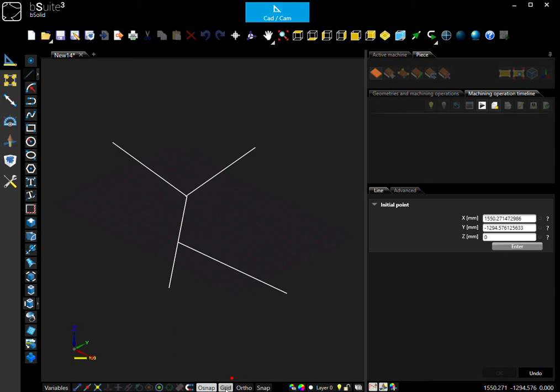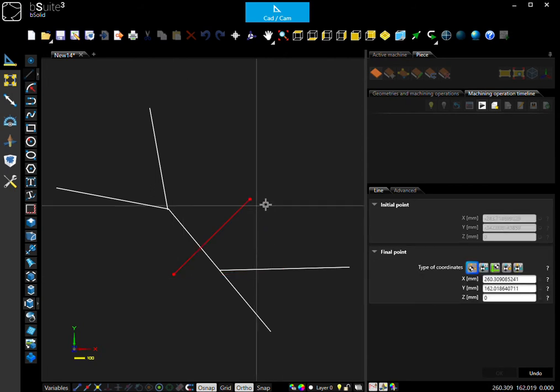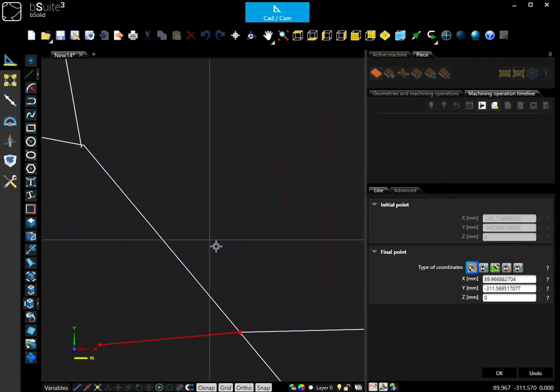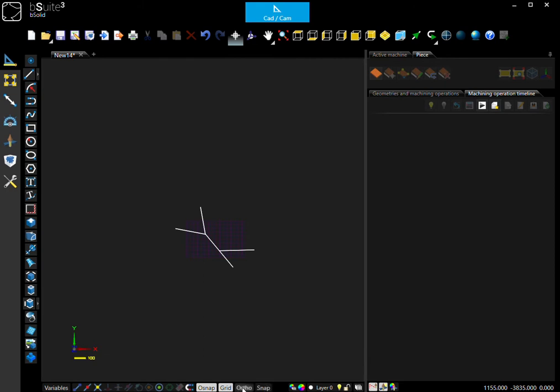You can also snap to a grid. You can create an orthographic snap, so that will give you snaps that are at 45, 90, or the other increments around the axes there, or you can turn the snap on to snap to the grid as well. So if you've got grid snap on, you can see that purple grid in the background there, it'll snap to those. So use those as you need them. Really handy for creating accurate drawings.